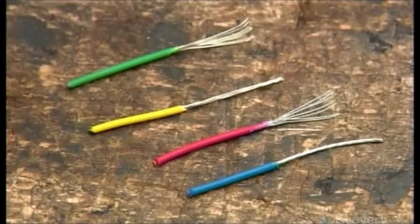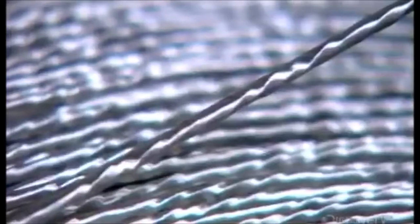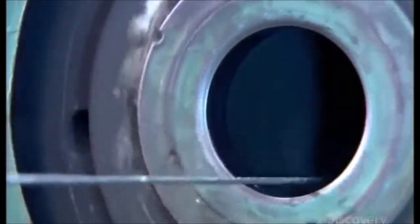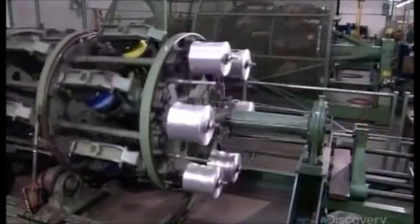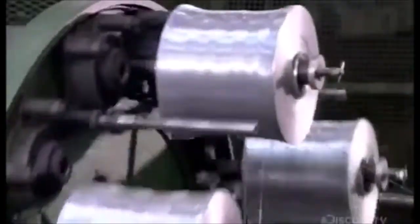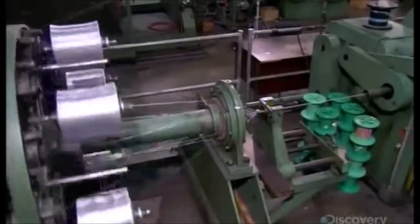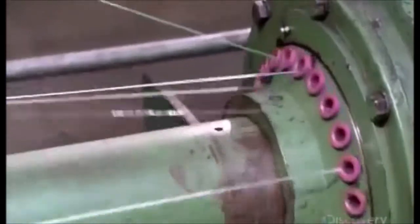The conductor then enters a machine called a cabler. It unrolls spools of insulated conductors and unites them with other components to form the cable's inner workings. At the center of this particular cable is a twisted pair of insulated conductors. Around them go color-coded insulated conductors and fillers to fill in the gaps between the conductors, giving the cable a smooth cylindrical shape. Here, the fillers are strands of polypropylene foam.